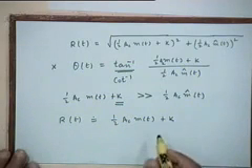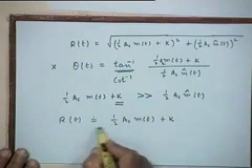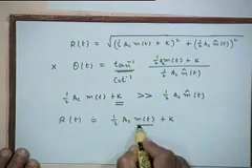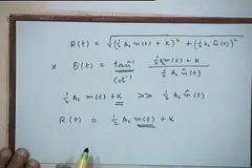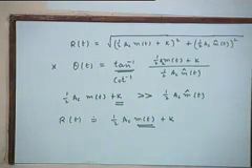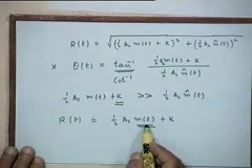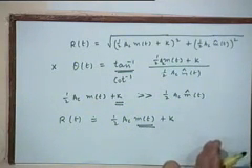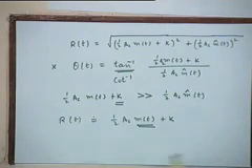And therefore if you ignore this constant, we got an envelope which is proportional to the message signal m(t), right? And therefore our envelope detector in that condition would produce an output proportional to m(t). You agree with that? If the envelope follows the message, the envelope detector obviously would produce an output which is proportional to the envelope.